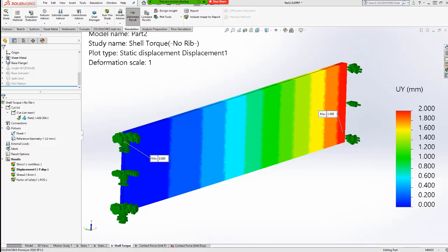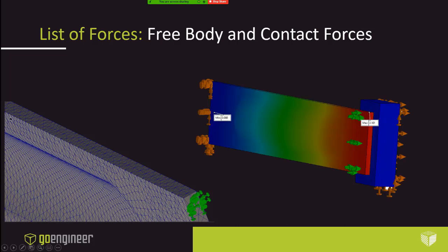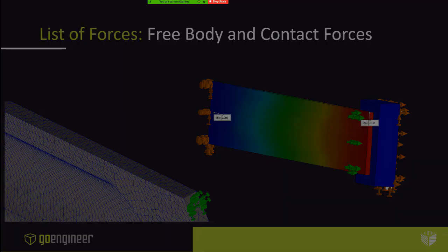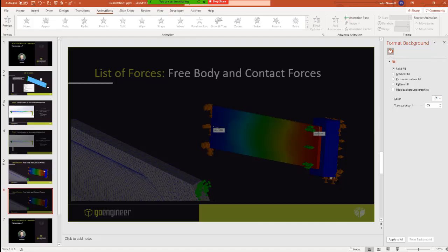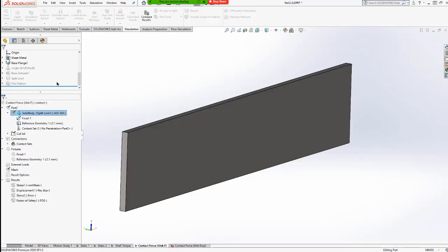Now we are going to jump back to talk about contact forces. Contact forces are when we'll be having surface-to-surface contact, sometimes node-to-surface contact, and we'll need to know how to interpret that, right? So for certain faces we'll just open a split line and show one surface to a surface. And the node to surface will show the criteria for that. Because sometimes our solids will need a little bit better definition.